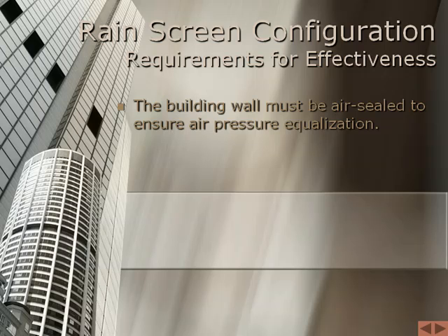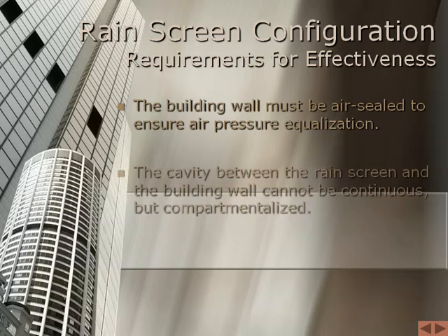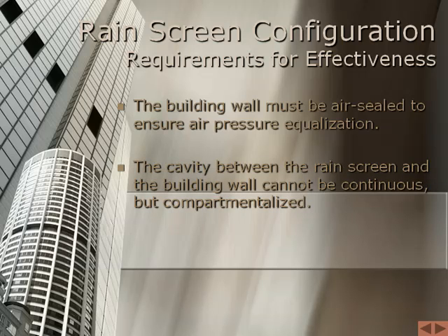Any rainwater that does penetrate the outer layer via vent openings because of gravity forces or capillary action or direct wind-driven rain should drain back to the exterior side of the veneer. Consequently, flashing details in the cavity that drain water back to the exterior are also very important. It is also important that the cavity space not be continuous around the sides and rear of the building. When wind blows on the face of the building, it creates a positive pressure on that face alone. However, a negative suction pressure is created on the sides, roof, and rear of the building.